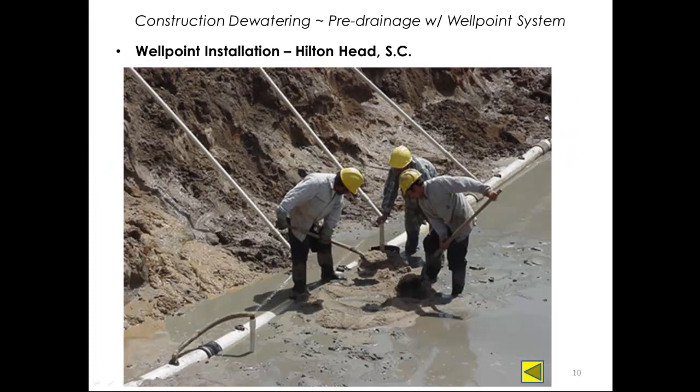Here we see a crew working in the Hilton Head area, and they're installing a well point system at the bottom of about a 15-foot excavation where the water table is. Here's the vacuum line, here's the flexible connection, and here's a well point that's already been installed.